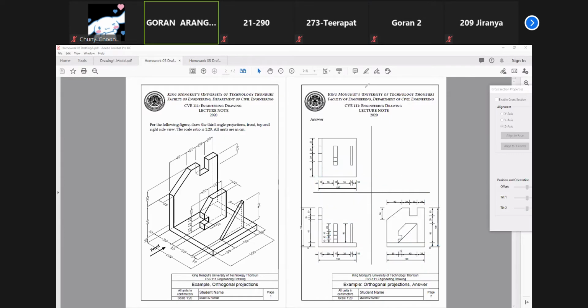The position of the folding lines can be placed anywhere you like. This is one example. So if you draw these folding lines, then you can start using the same height, the same depth, and the same width.